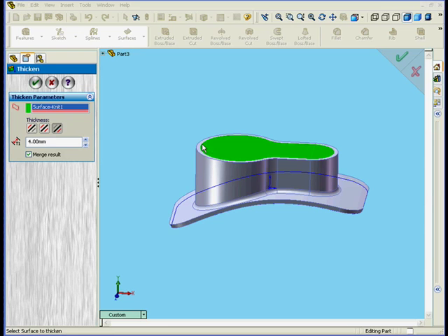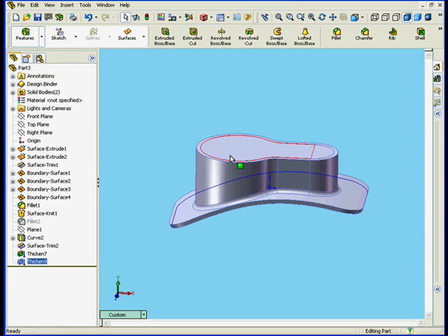Basically, what's happened? I had a 0 thickness geometry between these 2 solids. That's because I created these solids using options related to the outside surface. So there's a gap between these 2 solids. If I unselect the Merge Results checkbox in this control area, then I'm able to create the solid. Now I've got 2 separate solids.